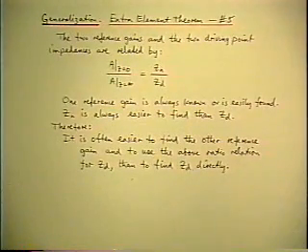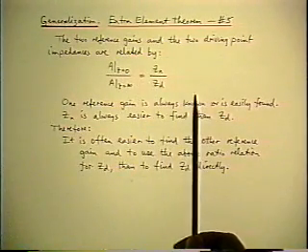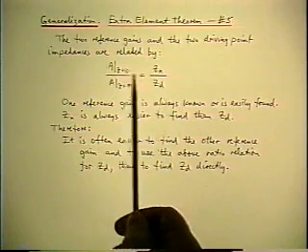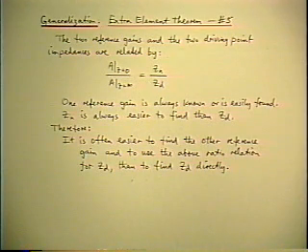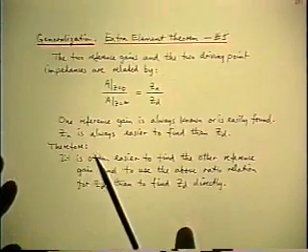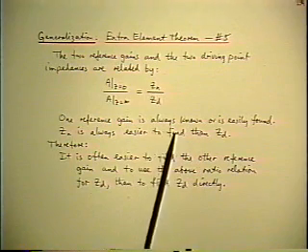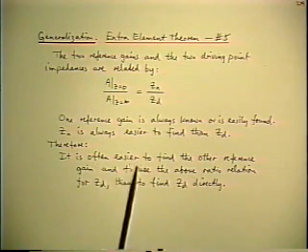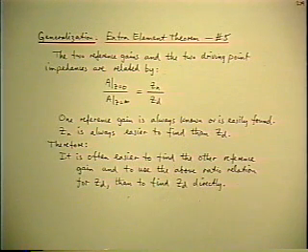So we've wiped out all the difficult part of the previous calculation. So this gives you another degree of freedom when you're applying the theorem, because of that redundancy relationship, you need only 3 out of the 4 quantities, and obviously you want to calculate the 3 easiest ones. And I think from this example you can see that quite often it might be easier to calculate the other reference gain than to calculate the Zd directly.